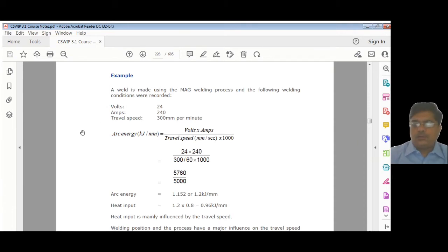You have to go with a tong tester, which is a multimeter, to the welder who is doing the welding. When he starts the welding, you have to take the tong tester and measure very close to his cable, which is using the electrode. If the welder is welding, at that time his holder will have the electrode a little bit, about 2 feet away. You can measure this voltage as close to his welding as possible.